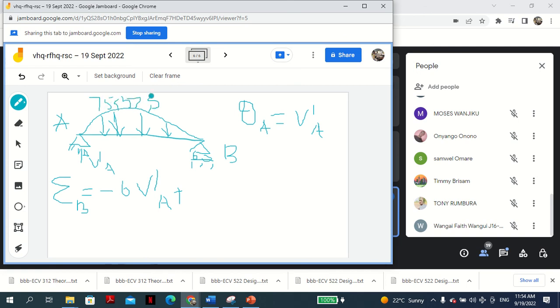Now to find the equation of this curve is easier, because now to find the area, you can see this shape is a little complex. So what do you normally do? Find the area times the distance to the center. The centroid of this, we found already to be about 1.8 from this end.